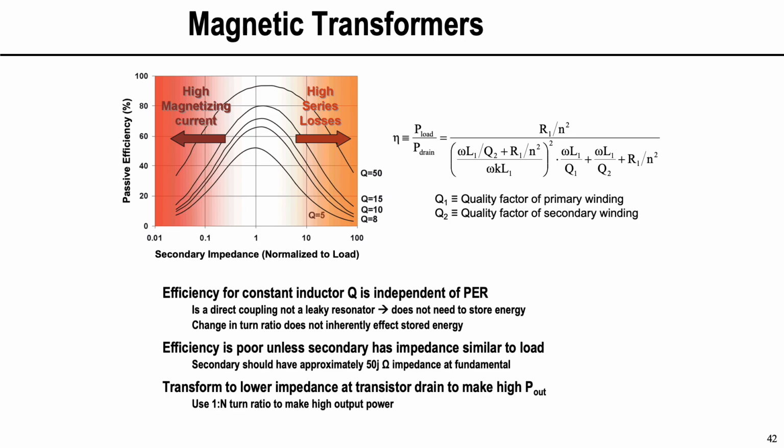Now, if you use a magnetic transformer, you can actually derive the efficiency in terms of this power enhancement ratio and other parameters. It's a little bit more elaborate calculation, and it's shown here. But in essence, you get some improvement. The improvement may not be as large. It's not exactly a proportional one like the simplified example that we showed, but it's a relatively decent one.